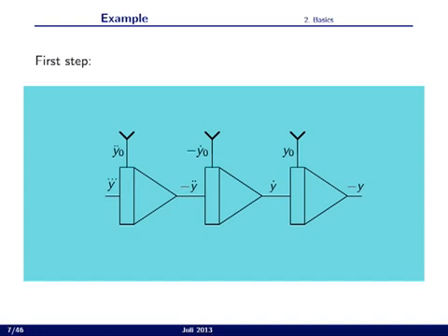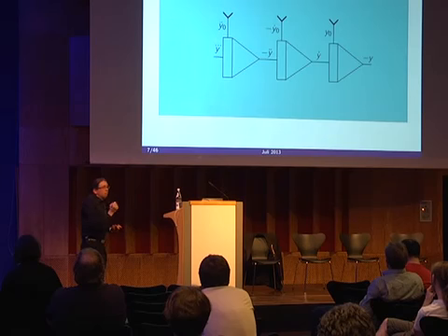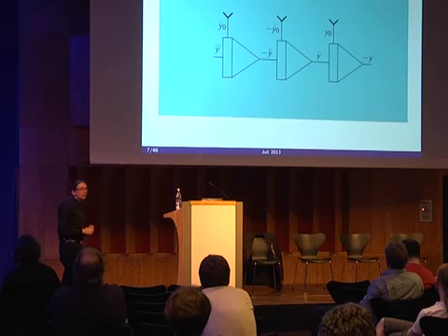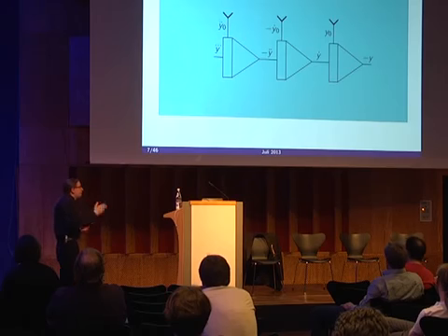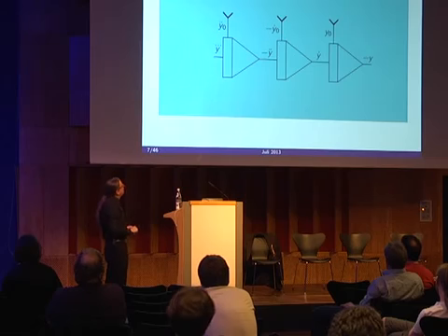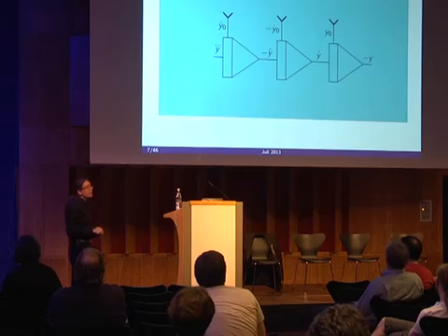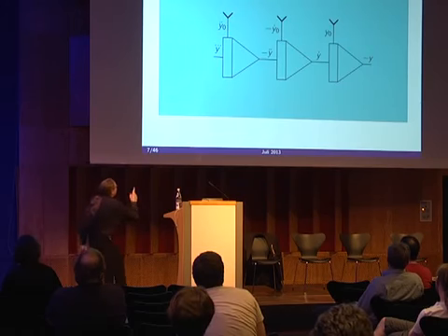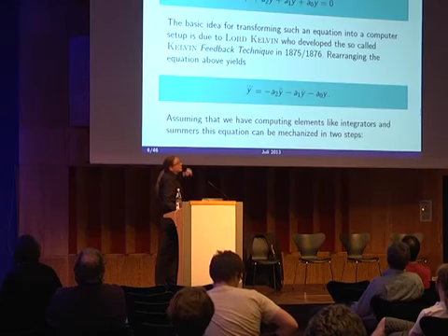And assuming you have an integrator, the symbol for an integrator is shown on this slide, you can derive lower derivatives from a given higher derivative. If I knew what y dot dot dot is, I could derive minus y dot dot. The minus is just for technical reasons. Ignore it. And by another integration, I could derive y dot, and yet another integration would yield the plain variable y. Now I have all variables which were part of the original equation.